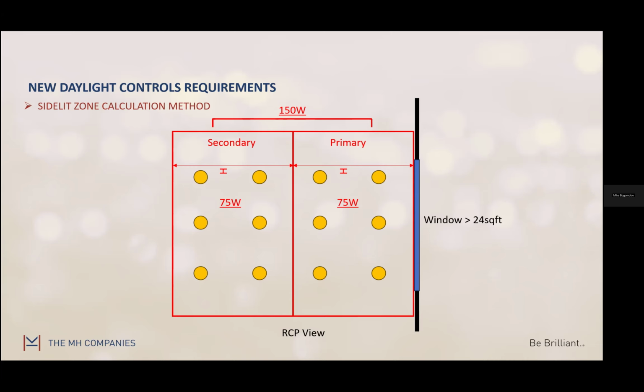It's mounted really close to the window, and you can calibrate an open loop photocell to run multiple different daylight zones. So in that case, you really only need one daylight sensor. Those are better for high mount applications because you're mounting it as close to the window as possible. It doesn't care if that window is 30 feet up in the air or 10 feet up in the air, because it's just monitoring the natural light coming in.